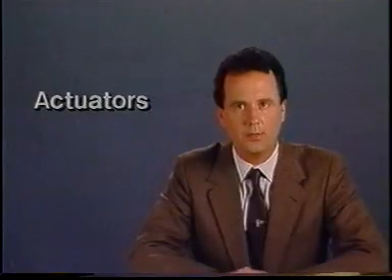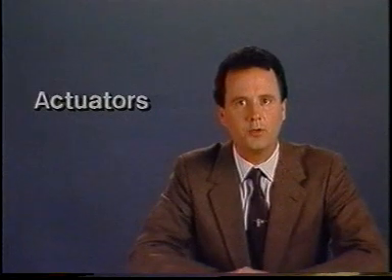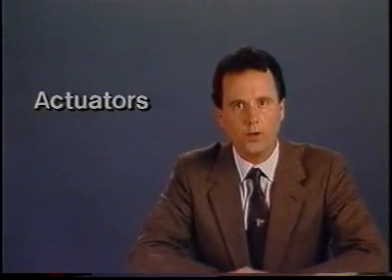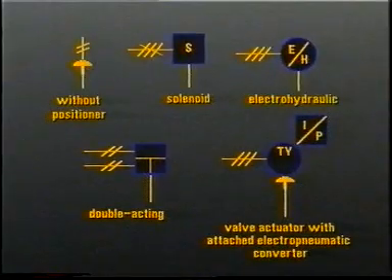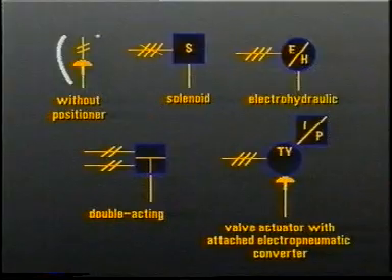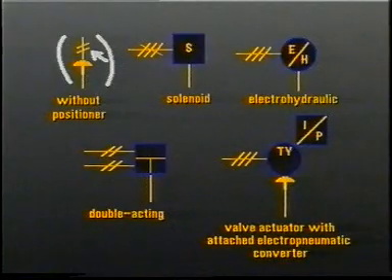Actuators are a good example of devices that are represented by a drawing that depicts the hardware. For instance, here is the symbol for a pneumatic actuator without a positioner. The 2 hash marks on the instrument line would indicate that the actuator is activated by a pneumatic signal from a controller. However, this actuator receives no feedback of the actual position of the device being acted upon.